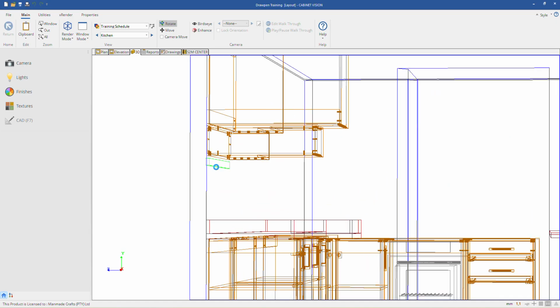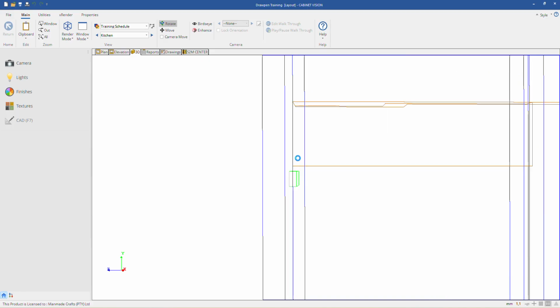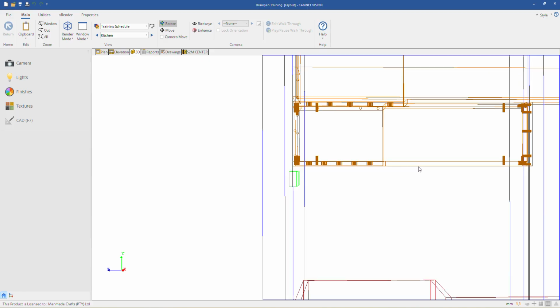If you place it, it's going to place flush against the wall at the back. I'm going to struggle a little bit to see yours because your kitchen is quite big. Just change your render mode to wire mode. There you'll see it. It always places flush against the wall. So I can use my outset values to place it underneath the center of the depth of the cabinet.